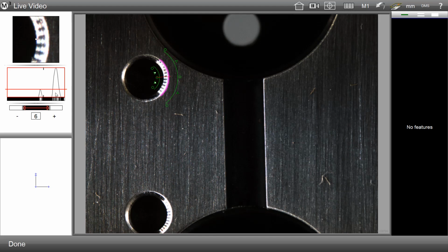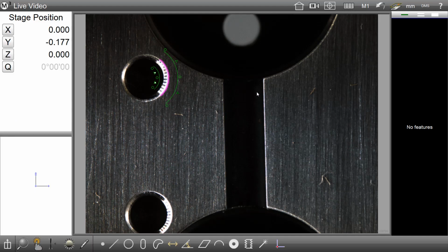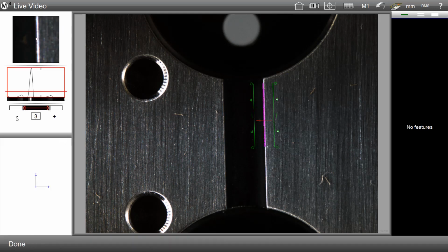Below the edge contrast data graph is the edge thickness filter. The edge thickness filter is in the unit of pixels. This filter detects the minimum edge thickness that will be detected by the current probe. The following shows a good example of this edge thickness contrast being applied to the current live video probe.